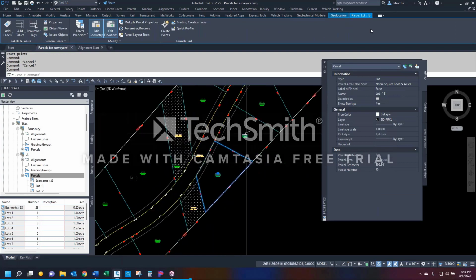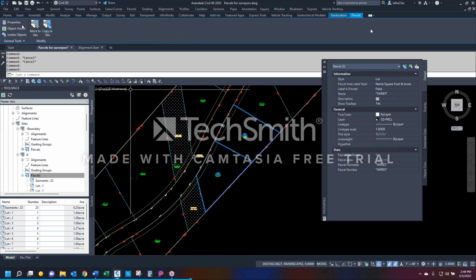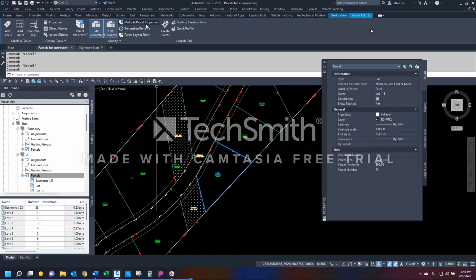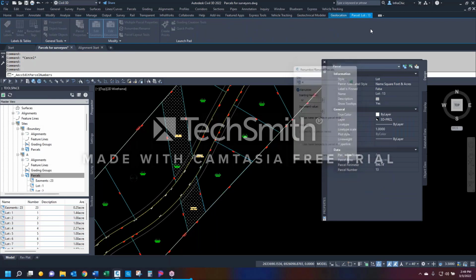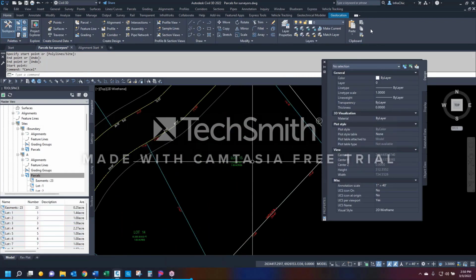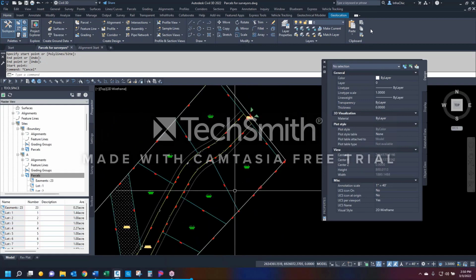And make sure if you grab more than one, this is what happens. Your ribbon does this move site, copy site routine. Hit escape until you deselect everything, then re-grab the label, rename, renumber, hit OK from lot 13 to the end. Ladies and gentlemen, we have an acceptable lot configuration of 15 lots.